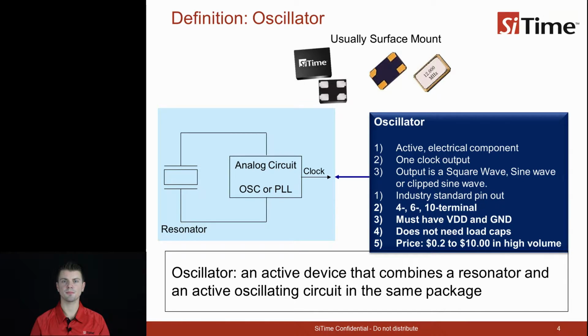Oscillators are usually offered in standard packages offered by multiple vendors. The package's nomenclature consists of the package dimensions in millimeters with the longest dimension listed first. Each dimension is listed as 2 digits to accommodate decimal values. For example, 5032 means an oscillator package which is 5 millimeters long by 3.2 millimeters wide. Common oscillator footprints are 7050, 5032, 3225, 2520, and 2016.